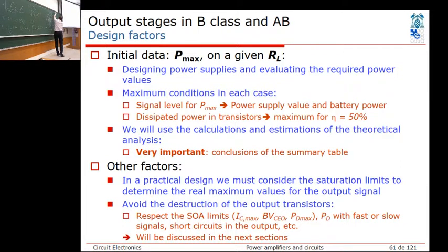What is the VCE here when you have negative signal? Okay. So that's one design consideration. So if that was, say, plus 20 volts, then you have minus 20 volts. The maximum, so this transistor VCE should withstand 40 volts of voltage. Okay, and of course that PD max.